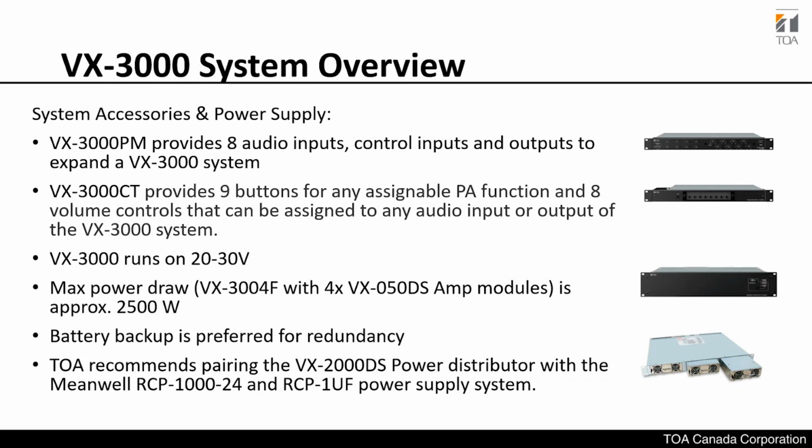So when the power fails, it switches over to the battery, and also built into it, because it's able to connect to the VX3000 system as well, you can program the system to send an email to any target emails in case of a failure. So there's live monitoring on the power, live monitoring on the speaker lines, live monitoring in case there's a short on the line. You can also program the system to detect that, or any failure of the system.